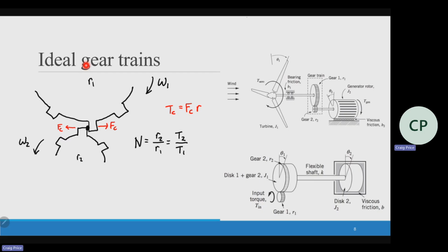That's really that torque that if I'm going from one to the other, if I'm stepping down my radius, so R2 is less than R1, then this torque is going to be lower than that one. But torque and speed are inversely related. So my omega 1 is going to be less than my omega 2. And you can go down the line with this. This is also the same relationship, not just of speed, but of angle. So I can relate it to theta.